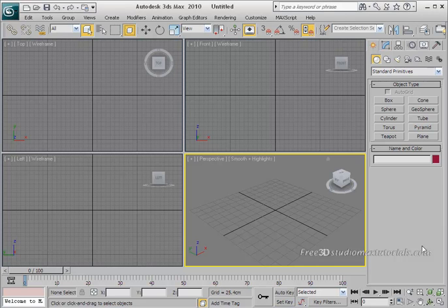So when you model a rounded object such as the helmet in this tutorial, we recommend that you avoid using a sphere as a starting point. The next illustration shows the polygons that make up a sphere. The top of the sphere is composed of triangular polygons whose vertices tend to pinch together at the pole. This can lead to problems later on. It is therefore best to model a rounded object other than an actual sphere using rectangular polygons only. You will use this technique in this lesson.